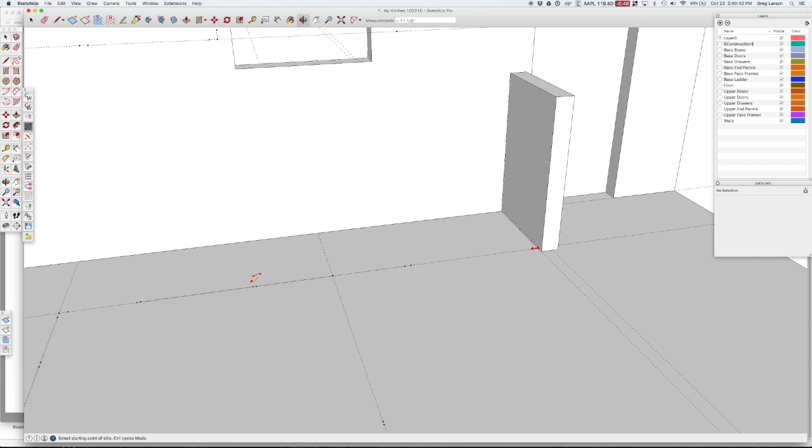And now I'm going to go down to this end here and choose my point where the opening starts for the dishwasher, and I'm going to go this direction to the right. Click here, and I'm going to call this a left end opening. And now we've defined the two ends of the cabinet, which you always do first in CabWriter. So anything in between is automatically considered a connector style. We'll talk about what that means in a second.